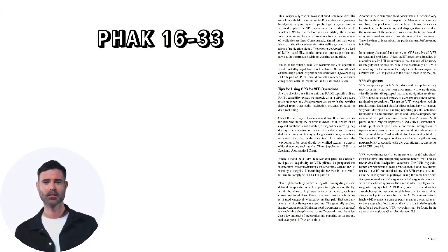Check the currency of the database, if any. If expired, update the database using the current revision. If an update of an expired database is not possible, disregard any moving map display of airspace for critical navigation decisions. Be aware that named waypoints may no longer exist or may have been relocated since the database expired. At a minimum, the waypoints to be used should be verified against a current official source, such as the Chart Supplement US or a sectional aeronautical chart.